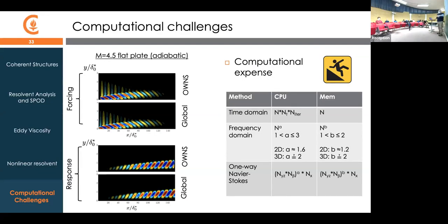It's linear algebra. But your point still comes back, which is that I chose a specific norm to optimize for my resolvent analysis, and that's completely arbitrary. That's up to you to define whatever metric you want. In the nonlinear part, we were using the shear stress metric, which is a little bit different, but everything else I showed you is optimized with a compressible energy norm globally over the entire domain.